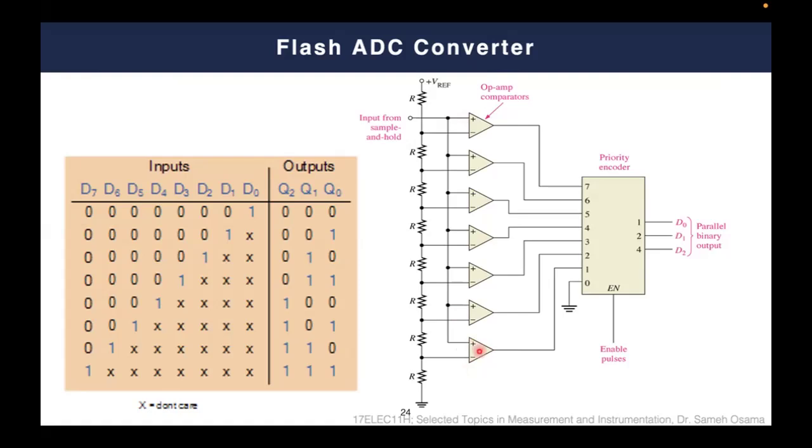So that means that you typically have, under the condition of 7 zeros, or say 6 zeros, 1 and 0. So here we have 6 zeros and we have only 1 here. So this is the first case. Now let's go to the second case, when this is 1. Once this is 1, the second comparator is 1, which means that your input is greater than 6/8 of the full scale. You don't need to see this one.